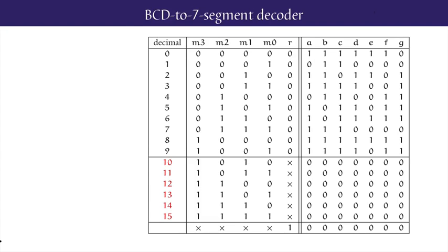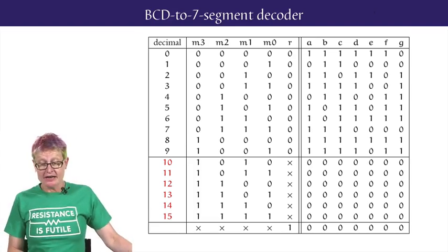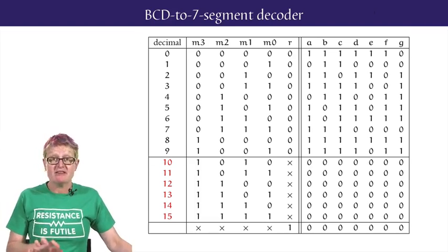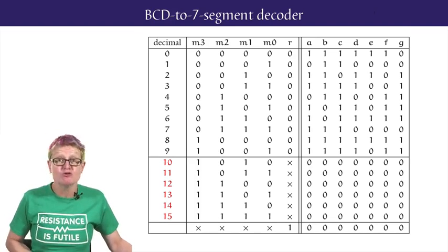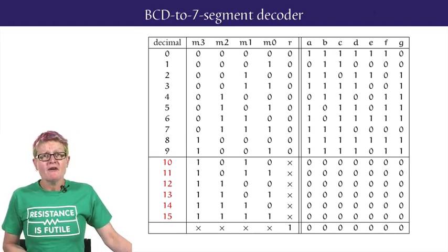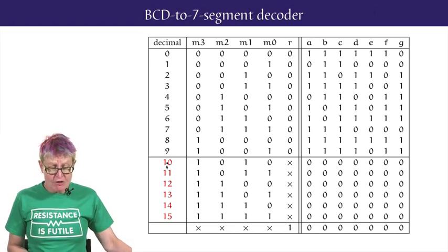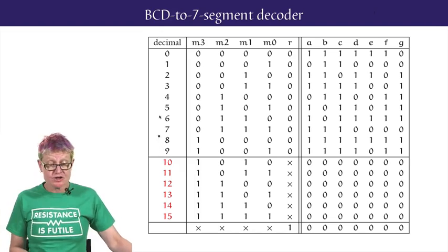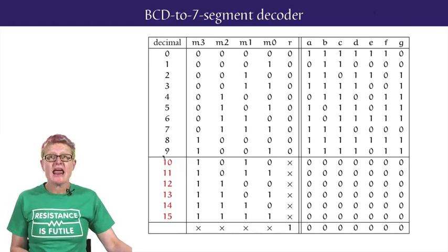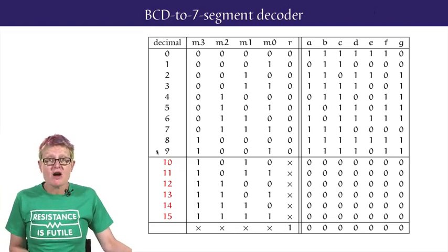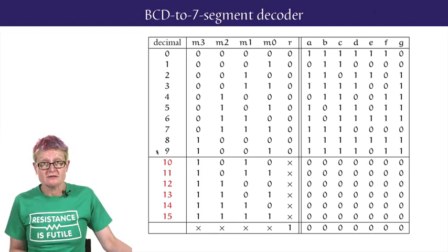Now, the truth table for the BCD to 7-segment decoder is as partially shown. Given 5 inputs, it should be 32 rows. For the intended lighting of the decimal values 0 through to 9, as shown in the first 10 rows, as listed here, you can check that we have the right distributions of zeros and ones.